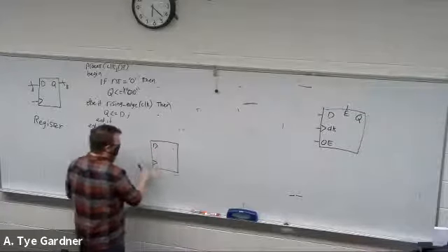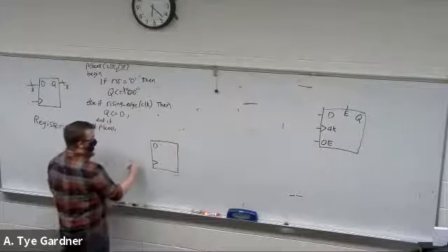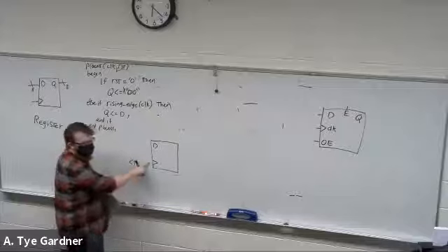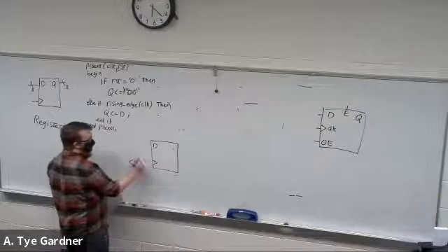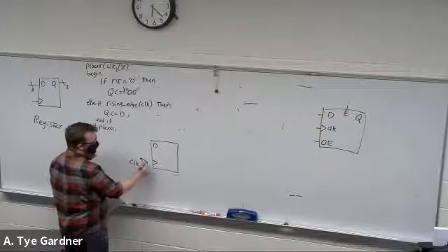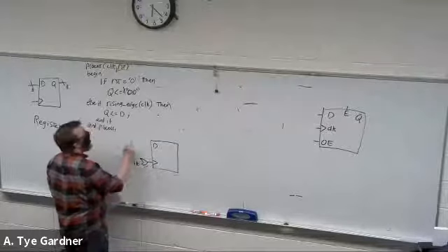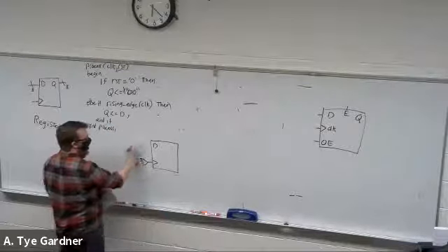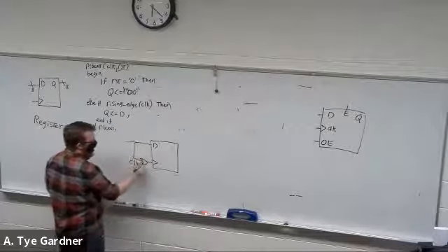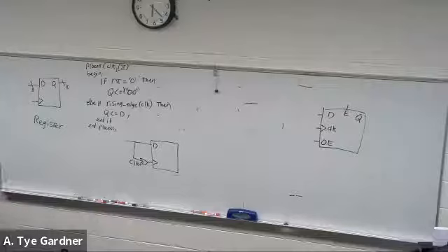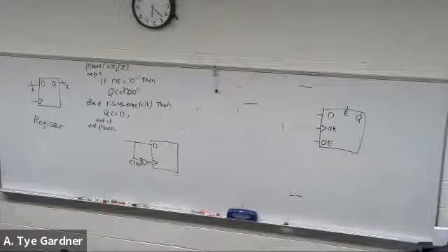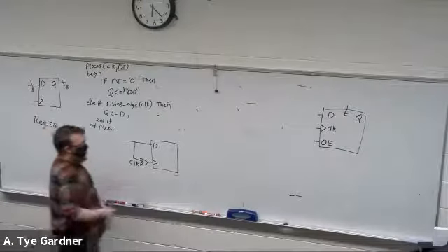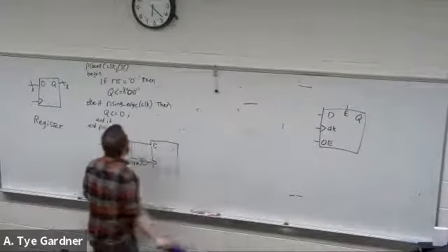So you have this clock, right? And you'd ideally have clock plugged into there that's rising edge. If I were to add D to the sensitivity list, this isn't quite fully accurate, but I kind of have done this, which is just nonsense, really. It would cause you timing issues all over the place.